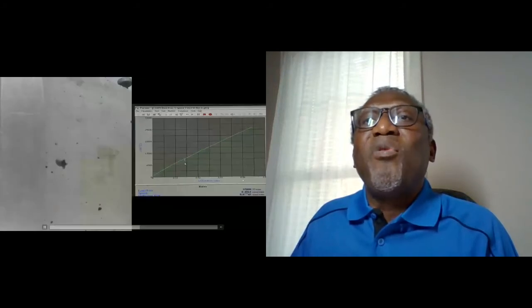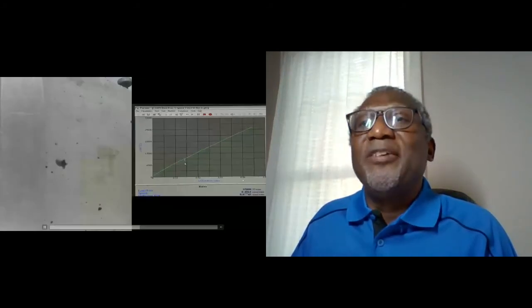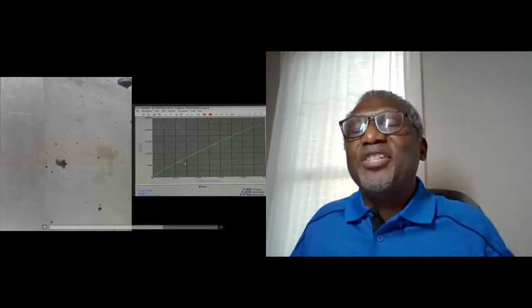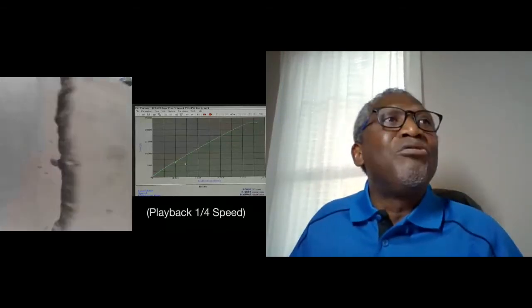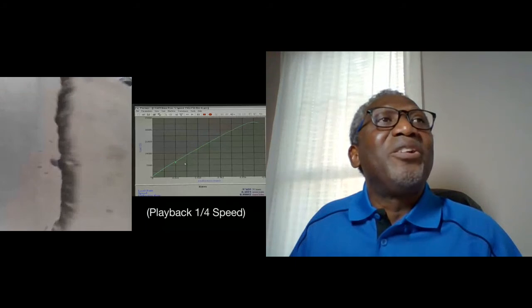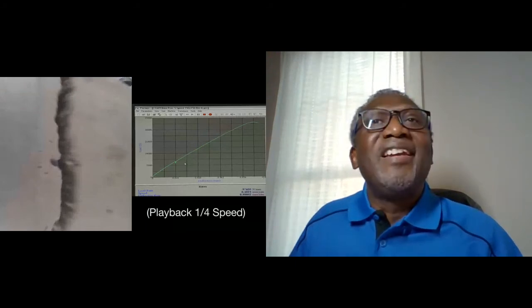We're down at 0.04, 0.05, compared to greater than 1 millimeter when the other one was stopped. And right here, you can also see what happened when it cracked. Essentially, because you don't have any fibers holding the crack together, you have a wider crack, and this also represents failure of the beam.